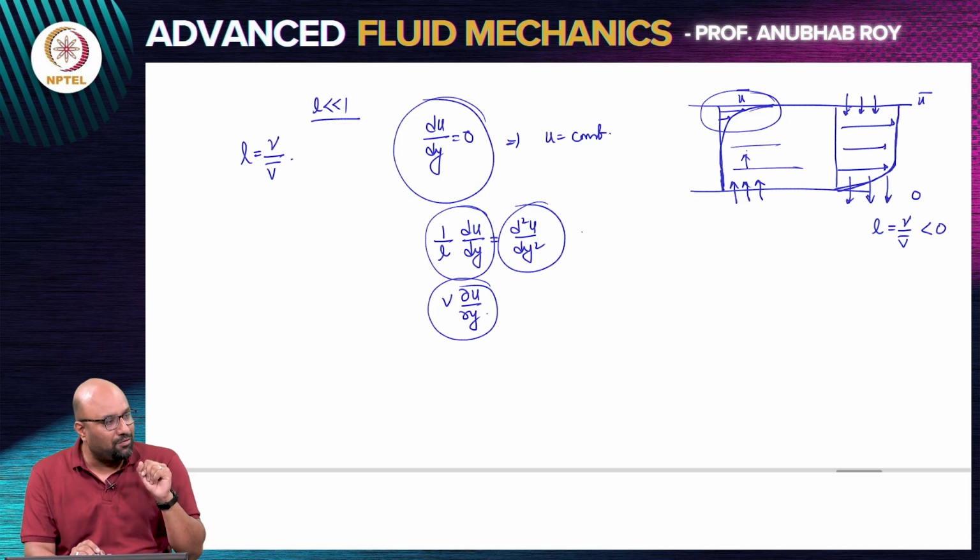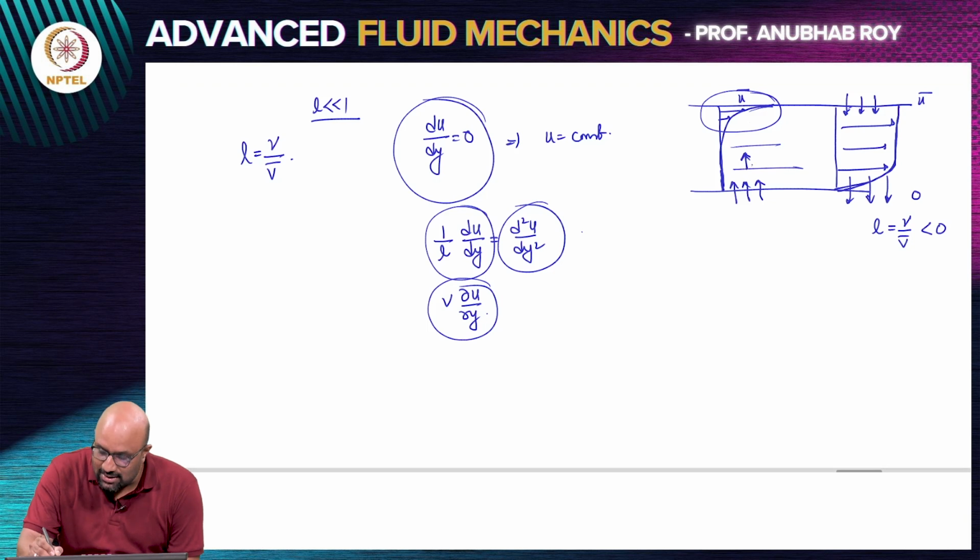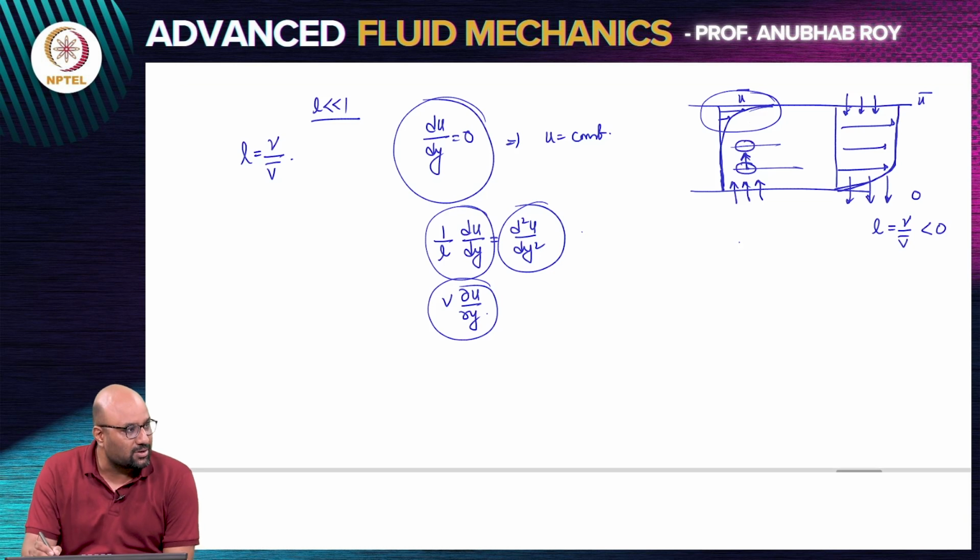Now what we are saying is that the flow has an x direction obviously, but it also has a y directional component. And we have chosen a very simple problem where the y directional velocity is constant. So there is a constant y velocity, but that is telling us something very interesting, that this transport in the y direction is taking a parcel here and taking its momentum and transferring it to a higher elevation. Now obviously in this particular problem, the fluid that is at the bottom level when there is a transport happening vertically going up is reasonably stationary. So the x momentum is very low. So you don't have a lot going on here. So the x velocity profile is almost 0.